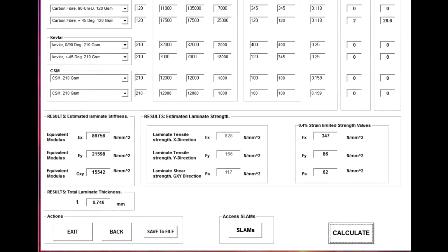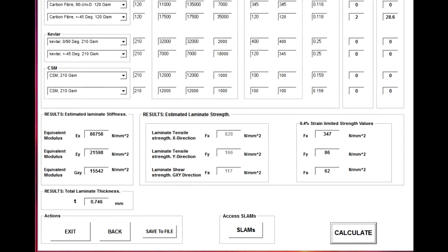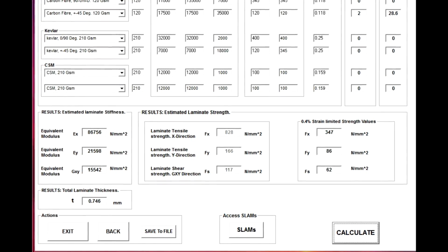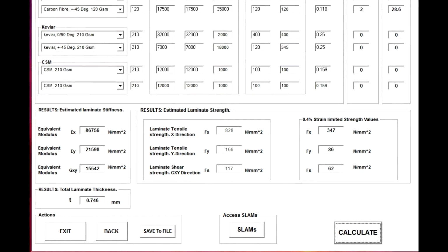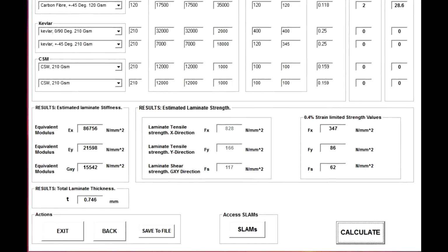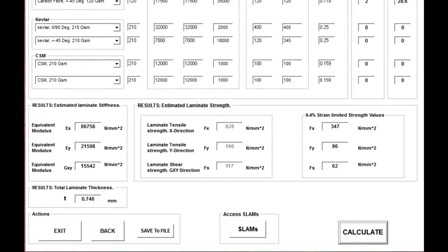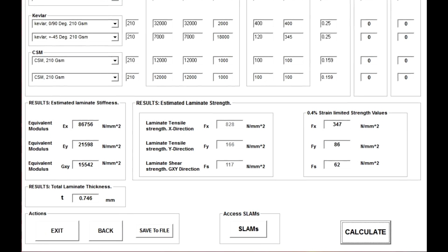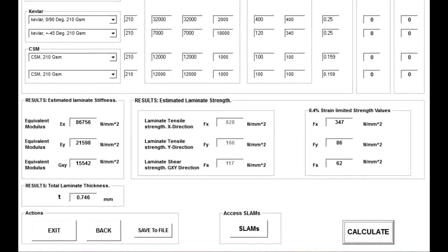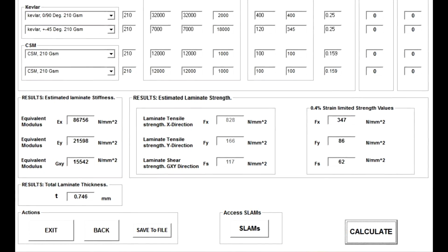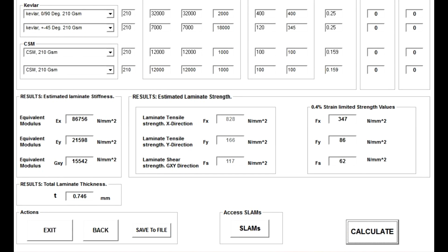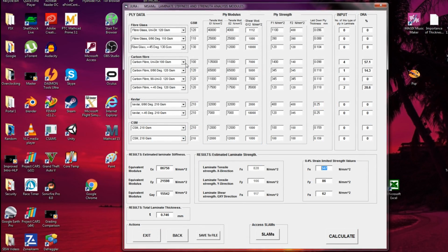So we see here, by increasing the number of unidirectionals, there's a tailoring effect, a bias effect if you wish, increasing the Young's modulus in the x direction. But this has a decreasing effect on the other properties, except for the thickness. Let's see what happens when we increase the grams per square metre for the carbon fibre unidirectional from 100 GSM to 180 GSM. Press the execute button, and now in the results box we will see